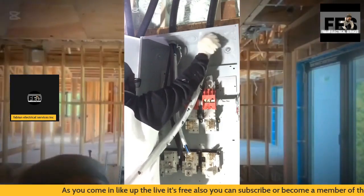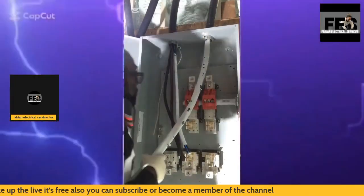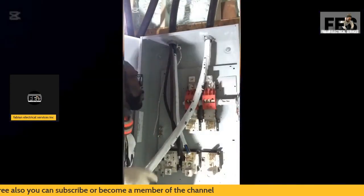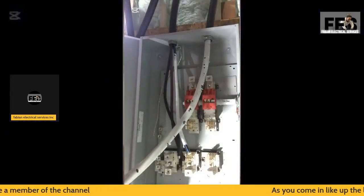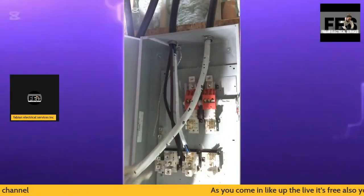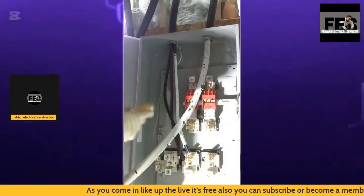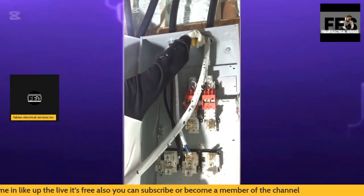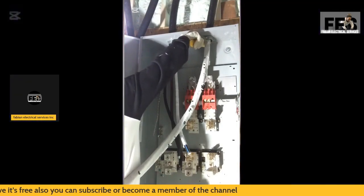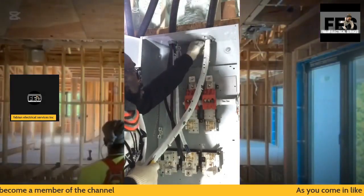So again, the reason that the disconnect is here and not at the 400 amp panel is because of the code rule that states anything that's within 5 feet of the electrical panel or the meter base shall have a disconnect, so there is no need for a separate installation of the panel right away.